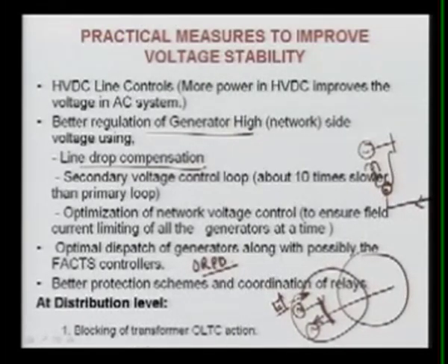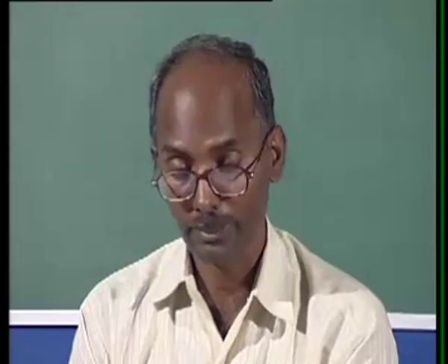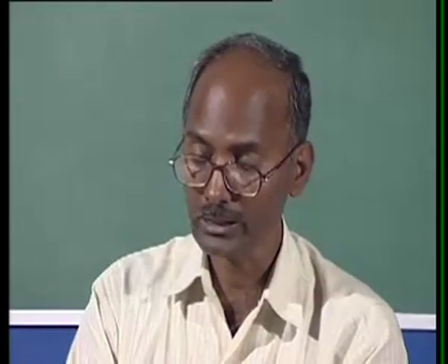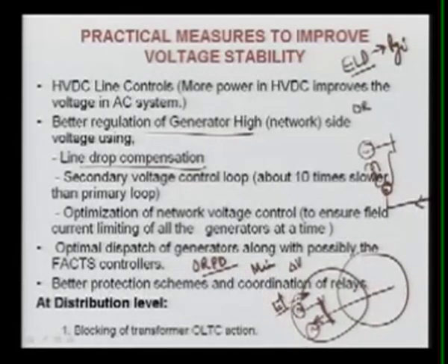where we minimize, again the minimization may be of any objective. Minimization may be of the voltage deviation. Minimization may be of the loss, subjected to the various constraints. Those constraints are your real power limits. Again, we are not touching the real power limit, because economic dispatch, that is called ELD, economic load dispatch, is where we set the real power generation output. However, in ORPD, we set the reactive power generation of the generators. So there your objective is the minimum cost of operation.